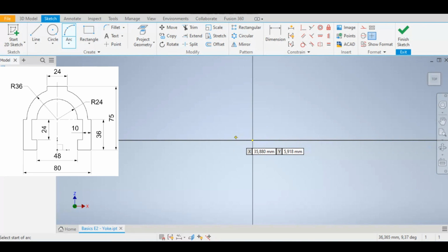I'm simply going to select my tab key on my keyboard, and that will automatically highlight my X value, my X coordinate that we want to enter. So from this, I'm going to enter 24 and my Y value will be 0. And once I enter tab again, you'll see a preview of your coordinates on your sketch plane. So as you can see, it's sort of where we would like it. So from here, I'm going to then press enter. So here you can see we have our coordinates, and from here we can draw everything from there.